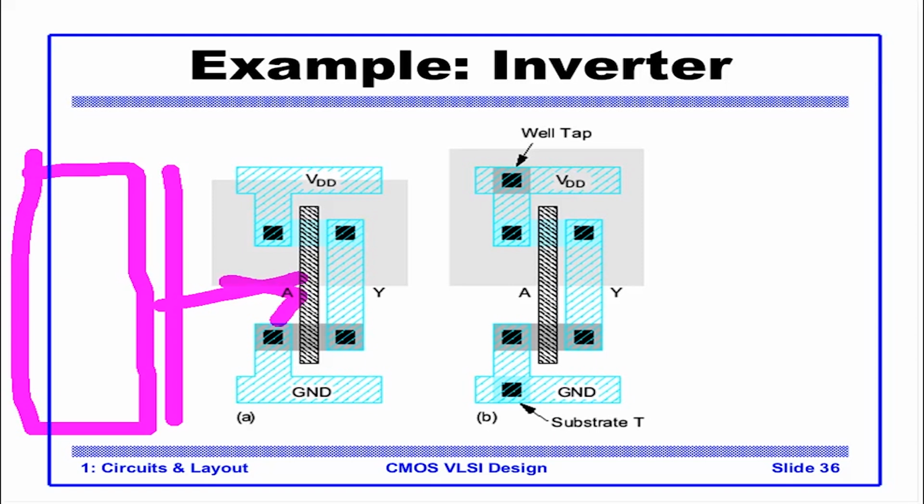So the VDD rail, if continued here, that is why I need to keep the height same, so that both of these cells can be placed between VDD and GND rails. So VDD and GND rails, the space between them, determines the height of all the cells. Right? They should be the same for all the cells in the line. There are exceptions, but only for very complex gates, not usually. That is why we say that all standard cells should be of the same height.